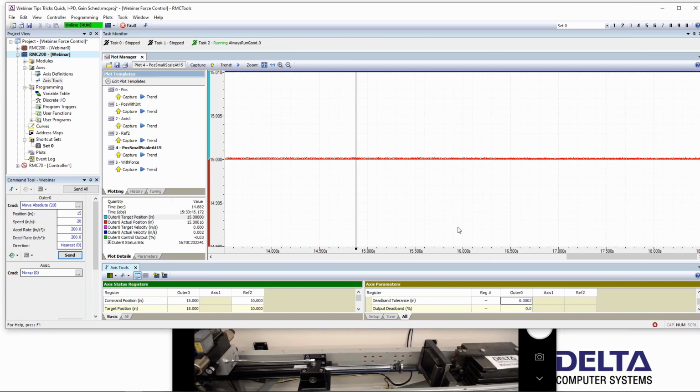So that's all there is really to the deadband tolerance and preventing oscillation. The valve I'm using here years ago, I started using it, really good valve, tuned up, great, held position. After a few years, I tuned it and it had this little small oscillation that I could not get rid of for the life of me. And I think it was just because the valve wore and who knows what's going on exactly at the zero position, and throwing in a little bit of deadband tolerance fixed it. We'll change the deadband tolerance back to 0 here and run, because for most of the things we're doing today, it won't make a very big difference.